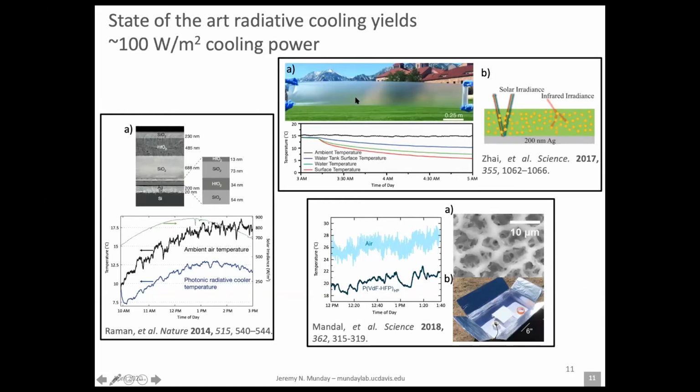But if you look at the optical properties, for visible light it's fairly transparent, but for these very long infrared light wavelengths that we can't see, it's actually very emissive. And so if you take this material and put it outside, here's a plot showing that the temperature of those materials can start to sink down, and it becomes lower than the ambient temperature here. That's a really interesting effect. Imagine going outside and some object cooling down when it's sitting in the sun.